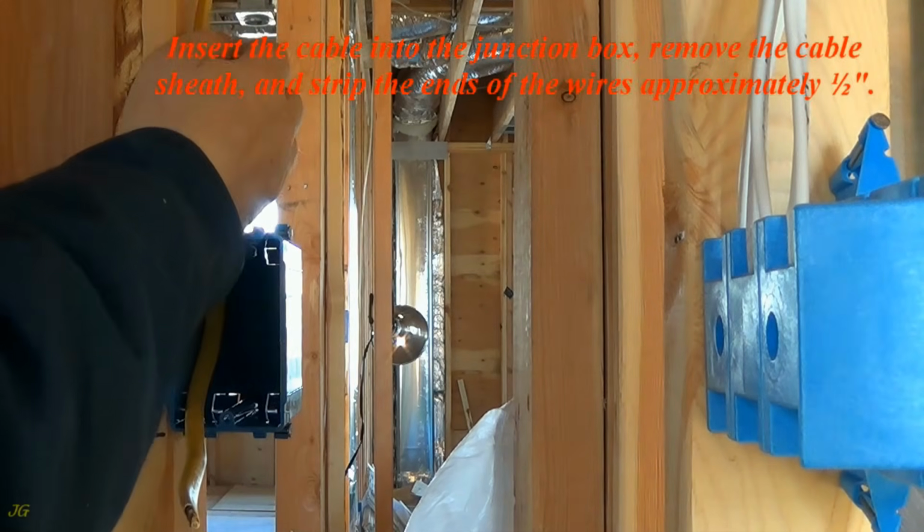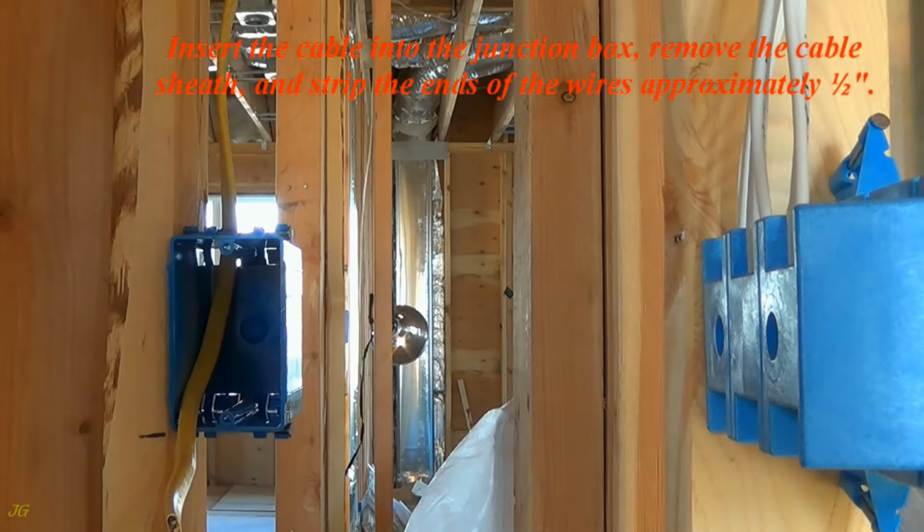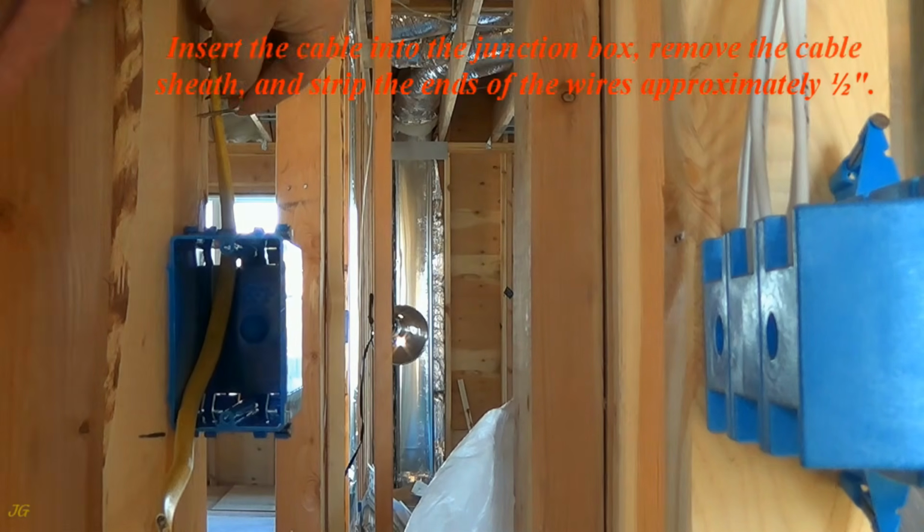Insert the cable into the junction box, remove the cable sheath, and strip the ends of the wires approximately 1/2 inch.